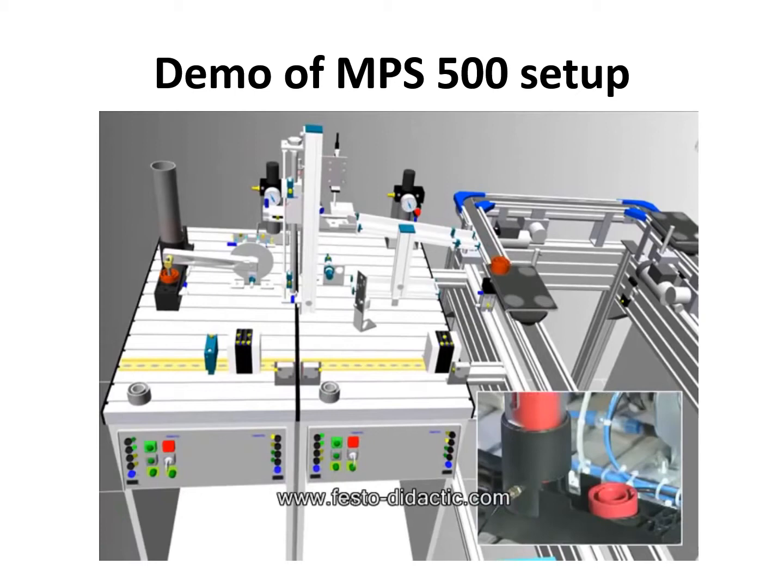So you could see we have pneumatic valves, okay, on the system. We will see the real picture of these valves in the coming sessions and slides. And we have a couple of actuators. We had one piston that feeds the part from the magazine forward, and we have this semi-rotary pneumatic actuator that passes the part to the next station.